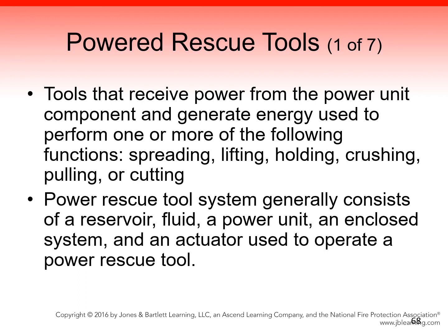The fluid used in the hydraulic rescue tool can be phosphate ester, ethylene glycol, automatic transmission fluid, oil, or a mineral-based hydraulic oil. Mineral-based hydraulic oil is most common. Each manufacturer may identify a specific type of hydraulic fluid that should be used in its product. Always reference the owner's manual to determine which fluid to use.